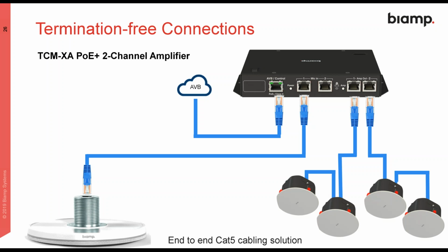The category 5 connectors, or category 6, should I say now. On all the pictures, all the schematics we've seen so far, there is not a single analog cable or speaker cable. Our thinking behind the Biamp conference room is we want to use category cable as much as possible to make it, well, first, more flexible, because then you can swap equipment around. Cheaper, because if you only have one type of cable in a room, it's cheaper to install and it's faster to install.